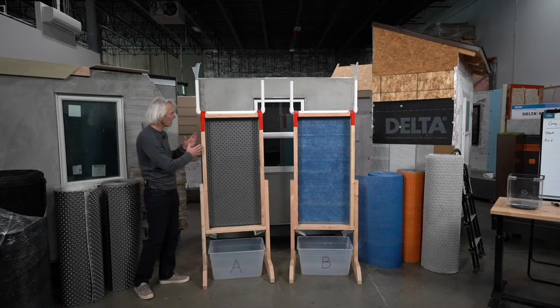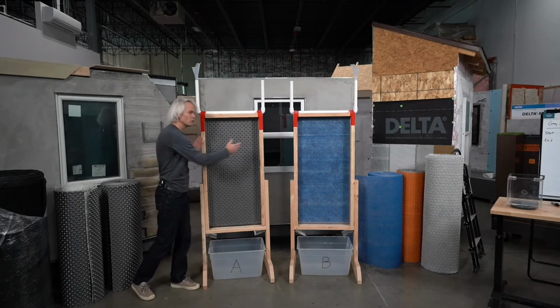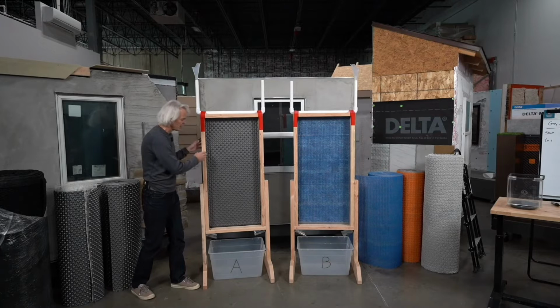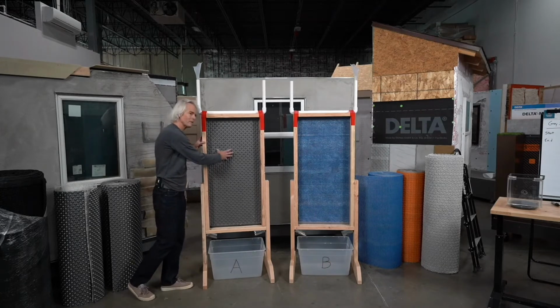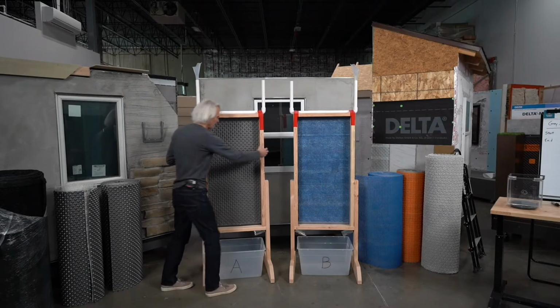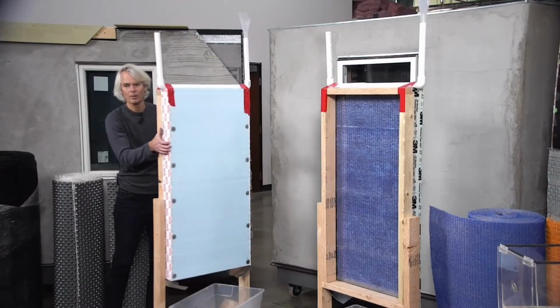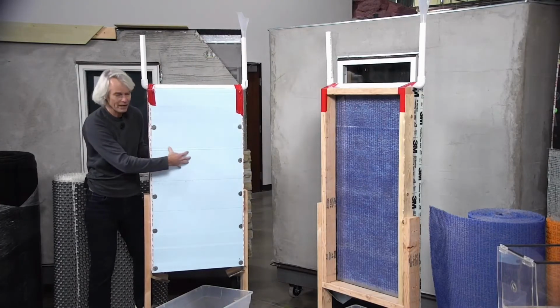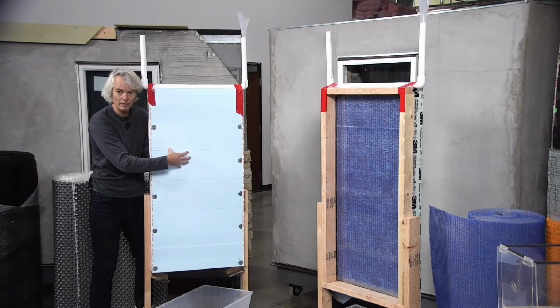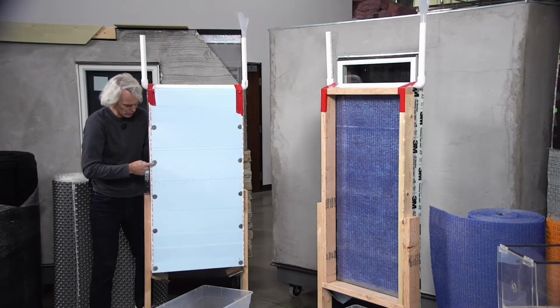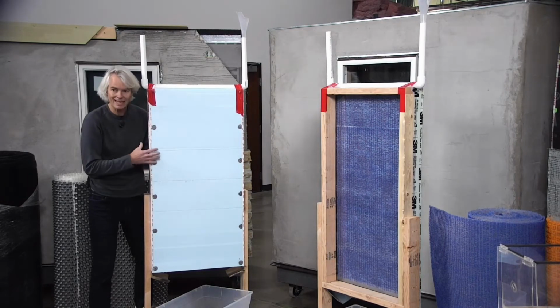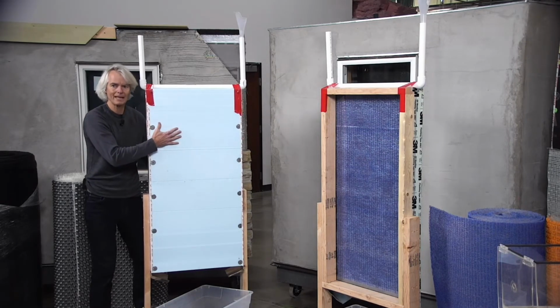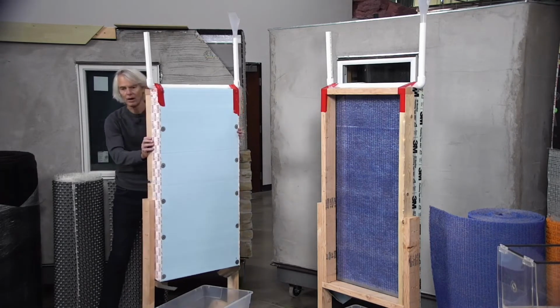So what we've done is we've built a frame. It's a 2x4 section of just wood framing, and there's a piece of Lexan here. And to push that rain screen product against that Lexan, we've taken a piece of 2-inch extruded polystyrene foam, and then we've screwed it very tightly down on the edges to try and compress that down here. So that'll be our test specimen.